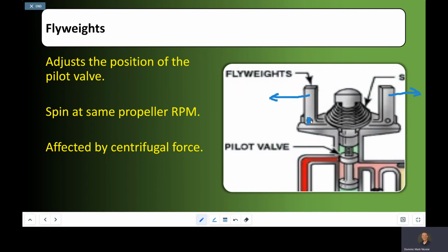And again, we got that pivot point on both sides there. So your speeder spring was pushing down on your thumb, but centrifugal force is pushing outward on the top of your finger. So what really comes into play here is how are those two forces balanced with each other? If they're equal, that means something. If one's greater than the other, that also means a couple of different things.